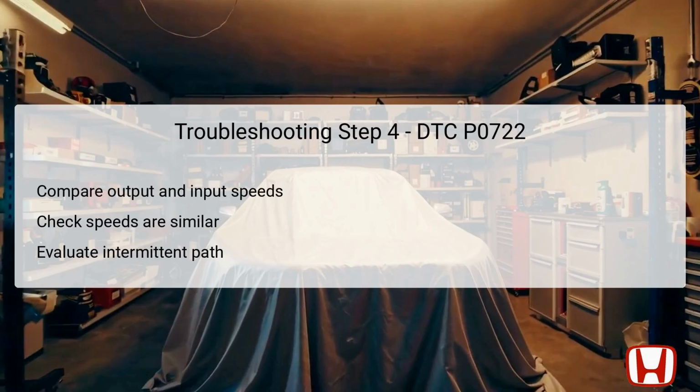Once you have the engine running and the vehicle in the appropriate gear, compare the output shaft speed and the input shaft speed using the HDS.